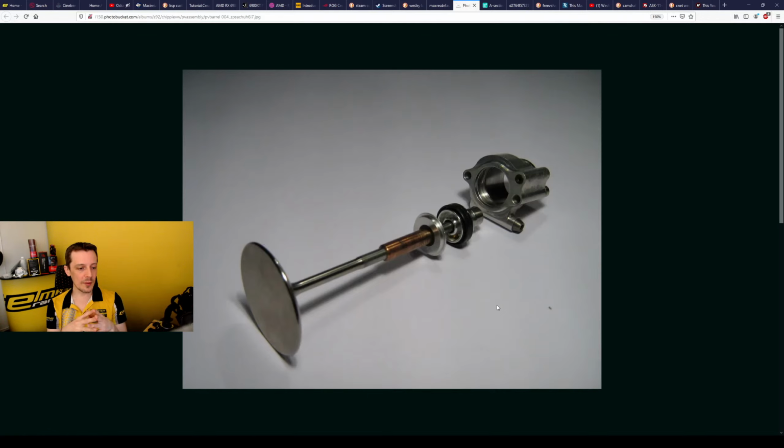But yeah, Inconel valves are really good for high temperature stuff, so exhaust valves typically, in racing engines, turbocharged engines with anti-lag or low compression engines where you have higher exhaust gas temperatures. So this is something that is good for that. Inconel is of course very heavy, so not really ideal for really high RPM use. Titanium again, titanium is theoretically good at high temperatures, but it's not as good as Inconel actually.